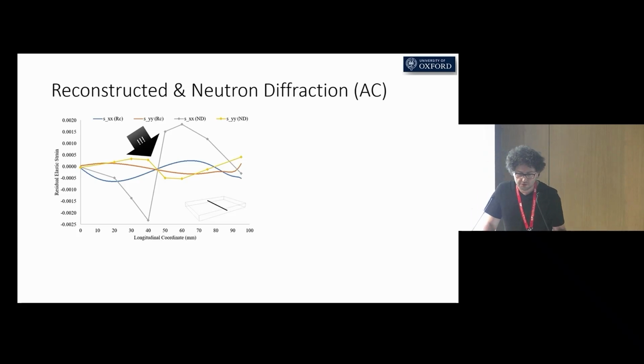What we can conclude is that both model calculations and neutron diffraction quantifications show similar distribution. The sign and the magnitude of these stress components switch at the end of the finite length weld bead. This is a good result because we can quantify a characteristic property of the distribution of residual stresses away from experimental data. This is the point. And that's it.